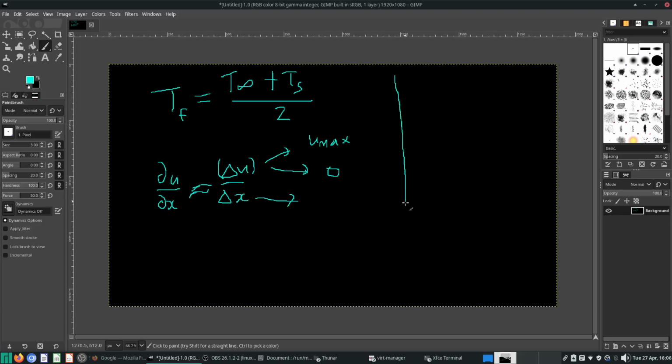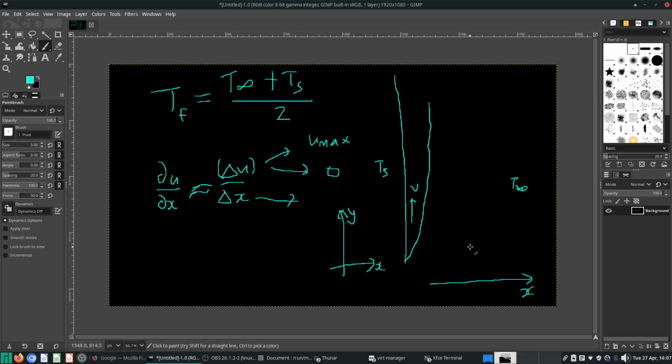I forgot to elaborate. When you talk about a natural convection boundary layer, we like to think of this picture. We have a wall here, and it goes up in the positive y direction. There's this hot wall with surface temperature Ts. To the right is the positive x direction. You will have fluid at T infinity over here. It will come into contact with the wall, and of course there will be this boundary layer that starts to form due to natural convection, because fluid close to the wall will get heated up and then start to rise. So you have movement over here, so you have v velocity, and of course where does the fluid come from? It has to come from the free stream. So u velocity is in a negative direction. This is the picture we are talking about here.